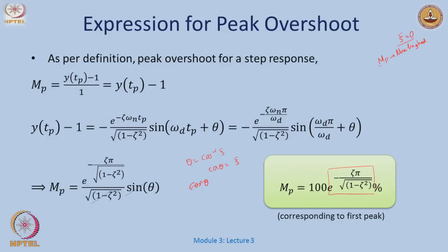Okay. So, if my steady state value is 1, then Mp here would be, I substitute zeta equal to 0, and so Mp would be 1. Which means my peak overshoot would go from this value 0 to 1, this is the desired value, it will go all the way till 2 and then come back and just keep oscillating like this. This is the standard response which we saw. It is almost like 100% overshoot.